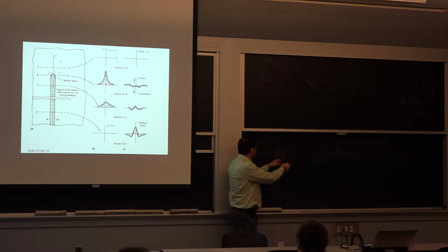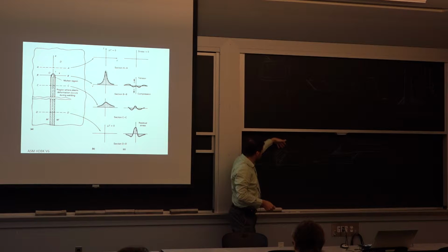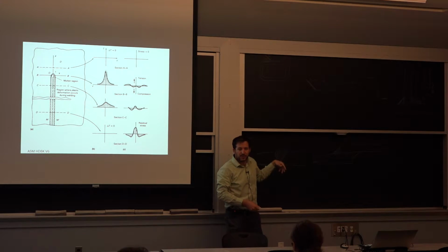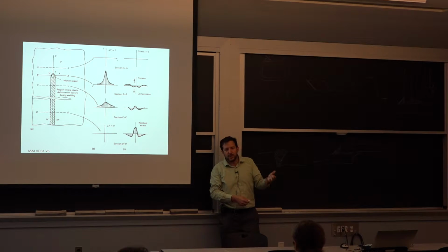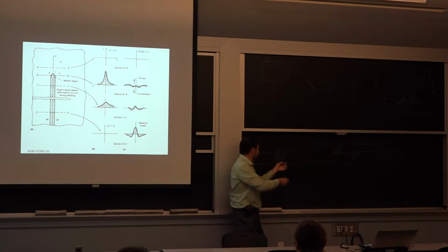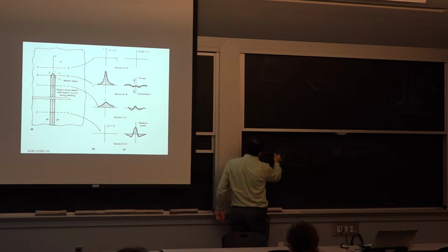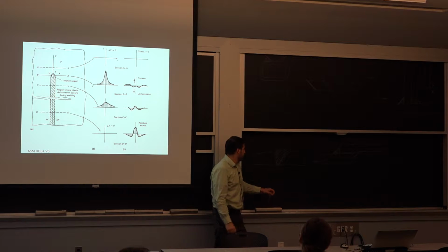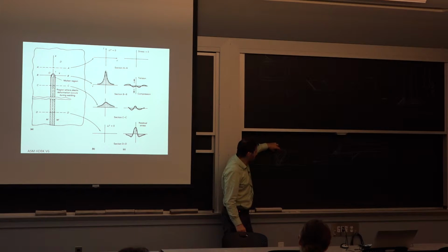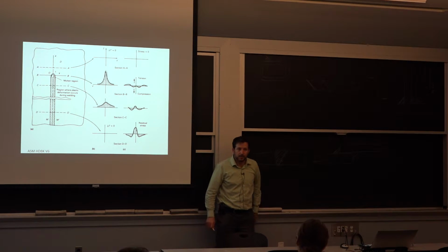If I take this weld, this plate, and I load it this way, there's a likelihood that I start a crack right in the middle that goes transverse. So that would be a category B or a category C because now it's the tension in this direction that's causing me trouble. But the tension that is the most problematic in general is this one here just at the toe of the weld. From the shrinkage here, you get the surface tension and it gets very close to yielding.